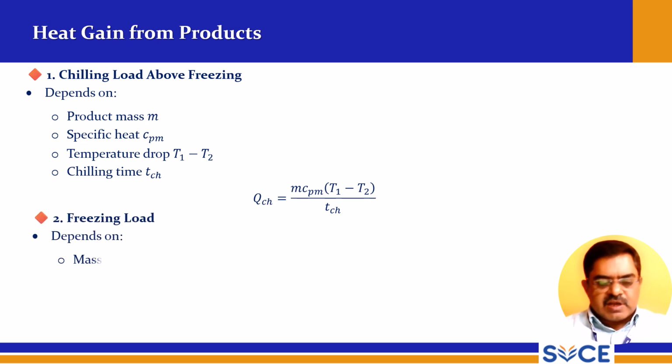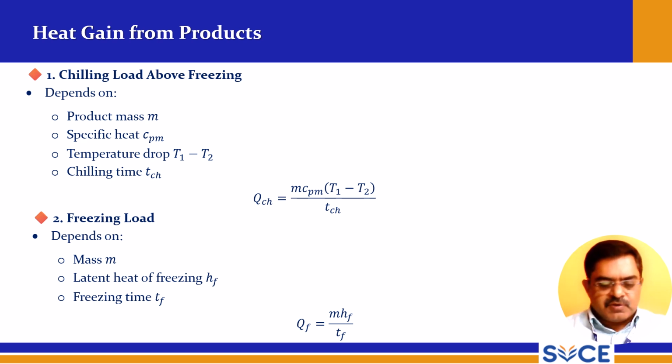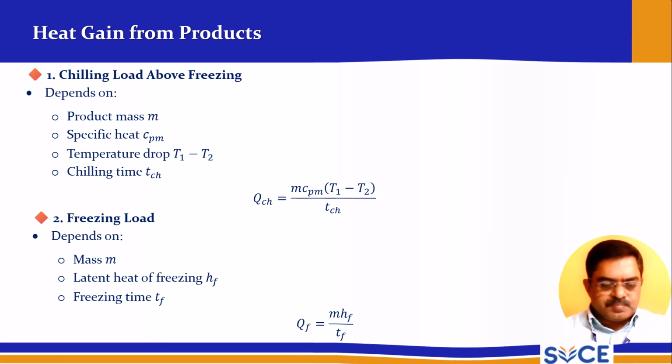And freezing load can be calculated like this. It depends on mass, latent heat of freezing HF, and freezing time TF. So QF is equal to M HF divided by TF.